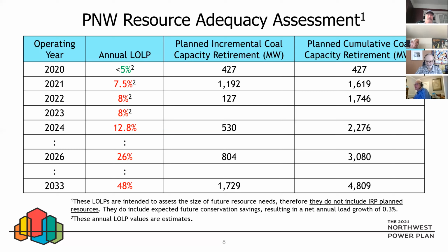And then, I don't think we were lucky, but in 2001 we had a very dry year with maybe some manipulation of resources in California, and we didn't have a blackout, but we had a very high cost year. In that year, Bonneville spent nearly $1.5 billion, mostly to pay the aluminum companies to shut down. Overall we lost about 2,500 megawatts of load out of about a 25,000 megawatt load system, so about 10% of load. Not all of it came back. The aluminum companies did not come back, or at least not most of them.